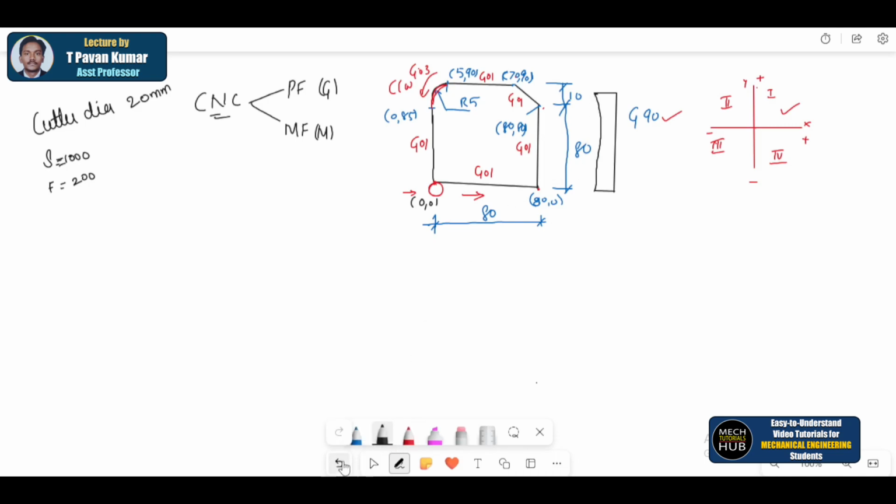Let us imagine the thickness of the plate in the side view is 3 mm or 5 mm or anything. Based upon the thickness, accordingly we will consider that as the end milling thickness or depth of cut. In a few cases, depth of cut will be given to you, say 5 mm. If that is the case, the depth is taken in the z direction.